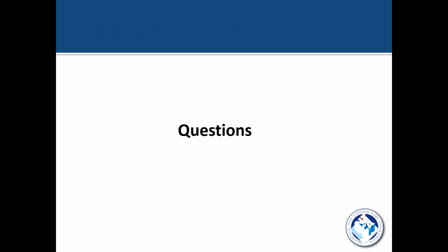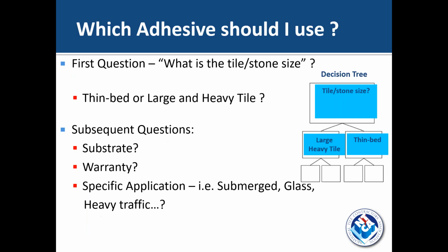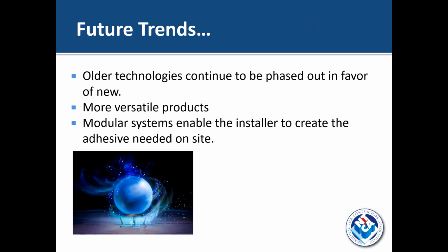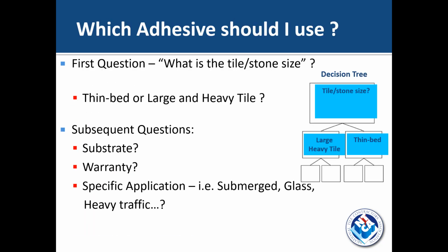3/8, I think anyhow. Yeah, 3/8. But really, the thin set itself, now that is fortified, has movement in it, and we'll take some of that movement in there. But movement joints are to be put in to help with that movement if the subsurface is moving at a different amount than, say, your tile or your thin set.